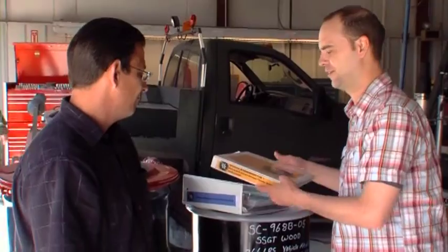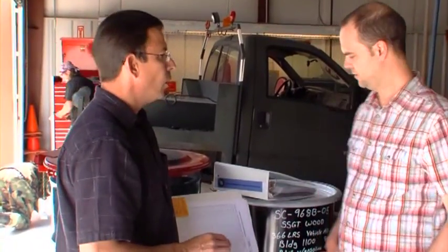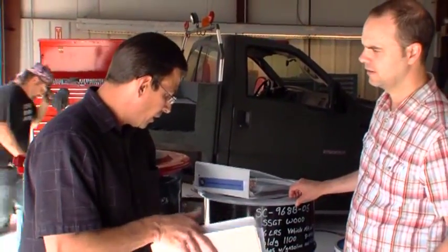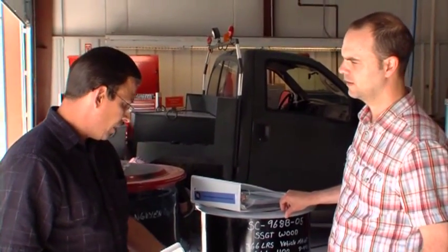Okay. Another thing that I wanted to ask about, since we've got these big giant manuals sitting here, I thought it would be remiss of me not to ask, what are these manuals and what's in them? Well, this first manual that you handed me is the weekly inspection checklist, basically. With anything, we have checks and balances to ensure proper management, part of that is coming out weekly and making sure that the barrels are not at capacity, that they're properly labeled, that names or numbers didn't get wiped off, that the secondary containments are still there and not damaged, and that the labels aren't rolling off and so forth. That's what this is for. The checklist covers all that sort of thing. It goes step by step, we go right down the checklist, and once we're done, we log it, and we keep a history of the logs of the checklists we've conducted.